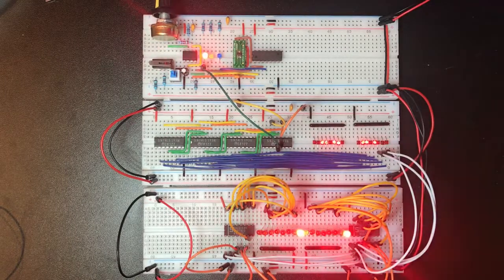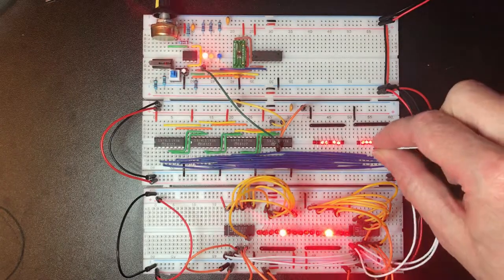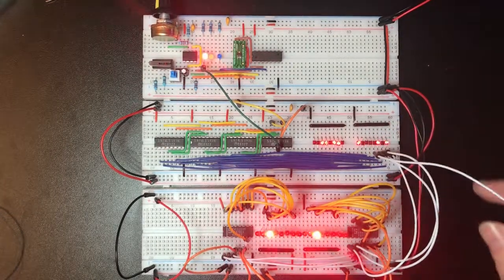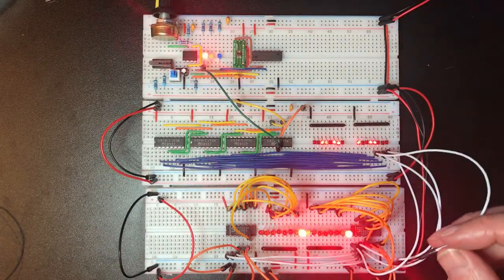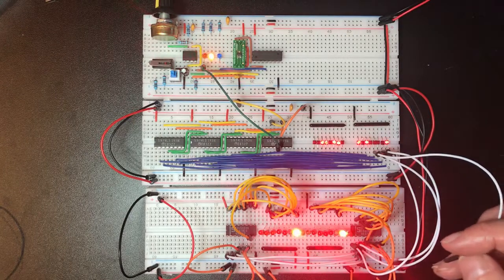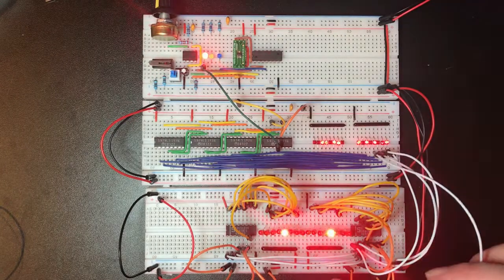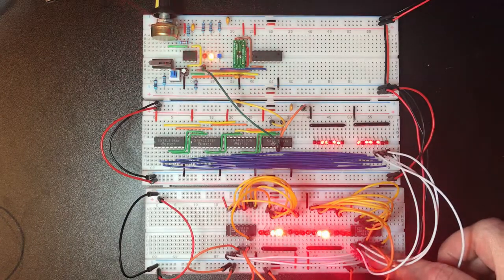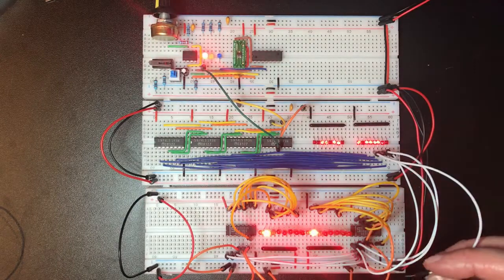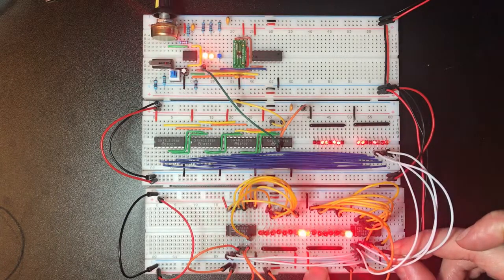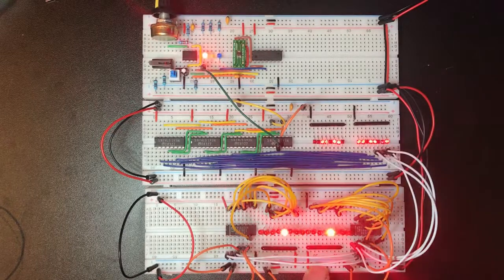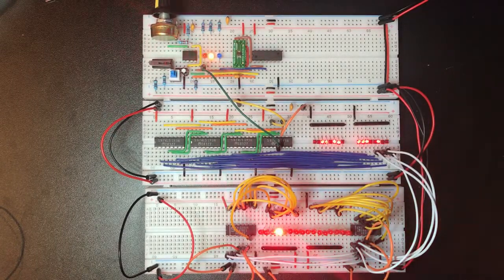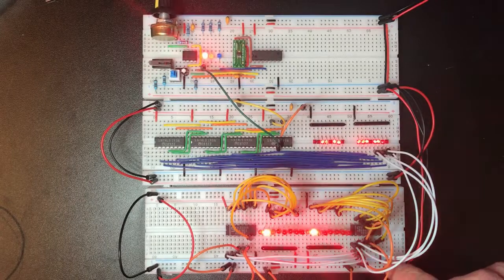So okay, what I'm going to do here, just to demonstrate this particular property, is grab the 4th bit from our counter over here, and there is no 4th select input onto these chips, but what I can do is replace this active high enable signal with this new selection bit.